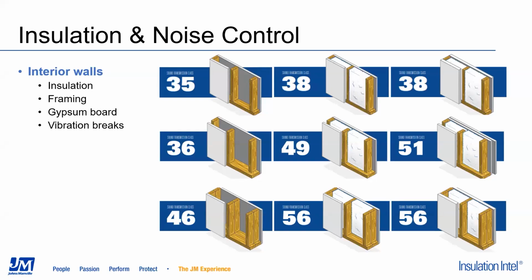So this slide is showing that as we add insulation going from the left column to the middle column, our STC rating is increasing. This is pretty significant in the bottom one, which is a double stud wall. And it's almost a 10-point jump. It is a 10-point jump.